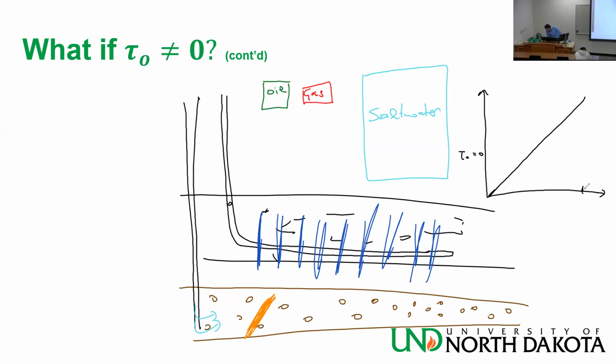The Mohr circle with sigma 1 and sigma 3 was like this at the old pore pressure. But then the pore pressure increased. So my Mohr circle moved to the right. This is the new sigma 1 and this is the new sigma 3. So pore pressure increased, Mohr circle moved to the right. And now I do have failure.